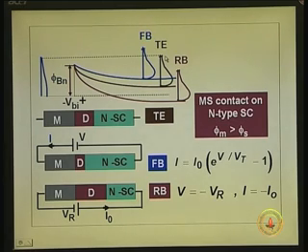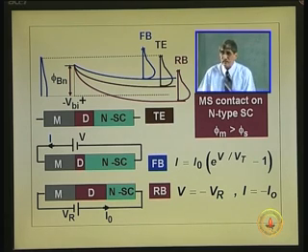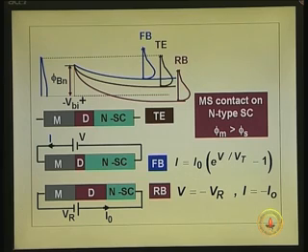We have discussed it more than once, but just put it in a different way, only showing the conduction band, because after all now the interaction is, if it is n type semiconductor, between the electrons and electrons. If it is p type semiconductor, we need not look into the conduction band at all. We look into the valence band, because the interaction is between the holes and holes, plus charges and plus charges, or absence of electrons and absence of electrons. That is the more correct term, because in metal people do not talk of holes as it is, but you can talk of absence of electrons, levels which are not occupied. So, that is actually finally what matters.